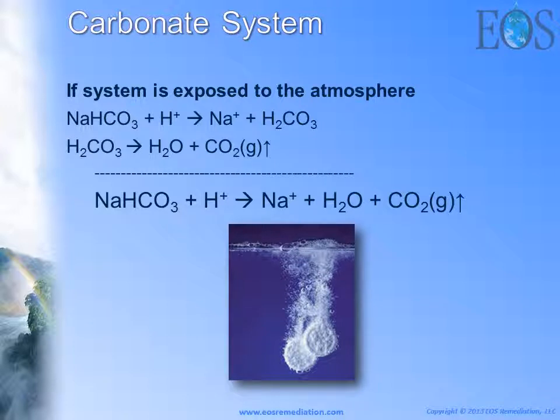First, let's talk about carbonates. So calcium carbonate, sodium bicarbonate, those are pretty typical buffers that are used for in situ bioremediation and pH adjustment. What makes carbonates an effective neutralizer or effective buffer to an acidic system is its ability to degas CO2. So when you introduce sodium bicarbonate to an acidic system, you're going to get sodium, you're going to get water, and you're going to get gaseous carbon dioxide. And that CO2 is going to need to effervesce, it's going to need to release to the atmosphere.